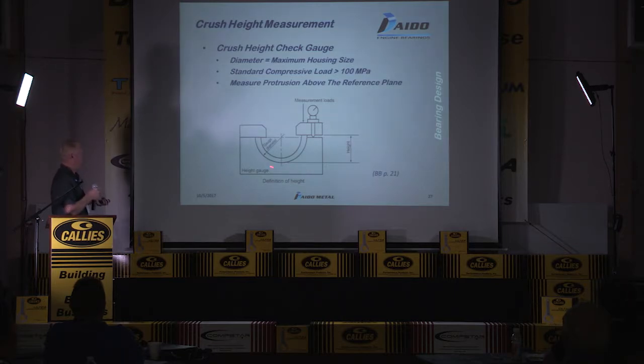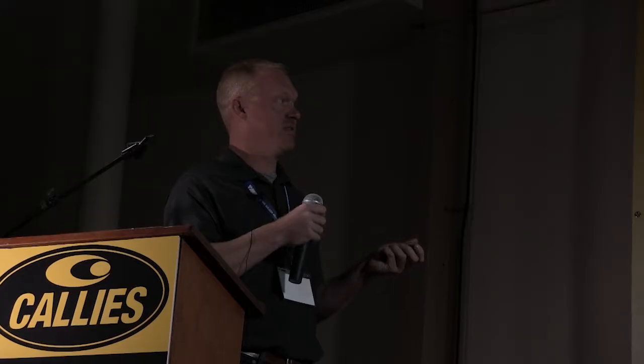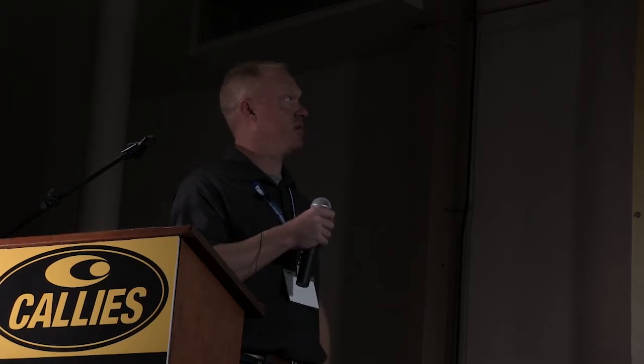And this is just a sketch of how we would typically check the crush height on a part. When a bearing is inserted into the gauge, there's a measured load that is put on one side of the bearing surface, and that height after the load is applied is how we measure the crush height.